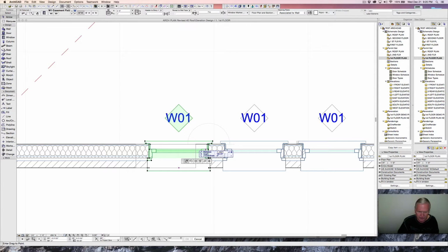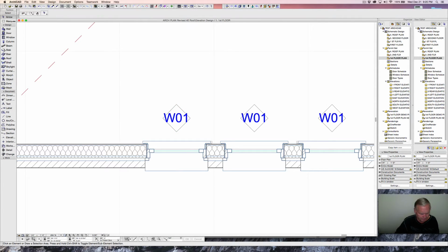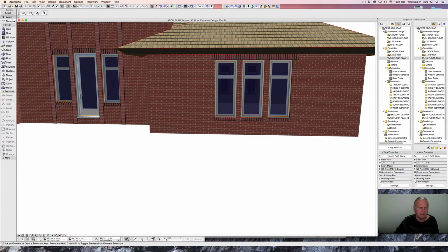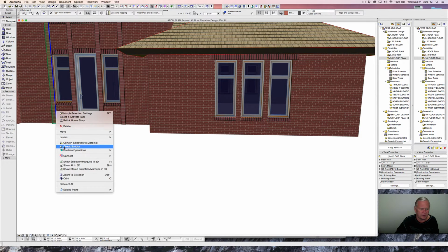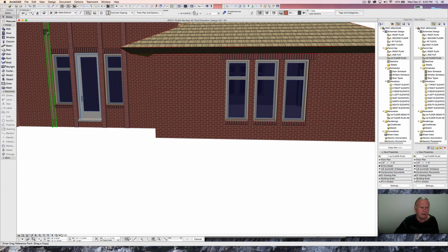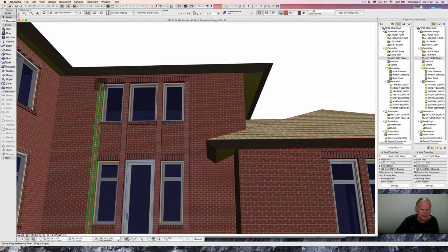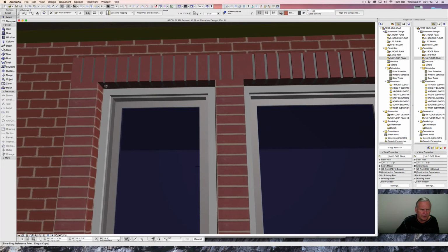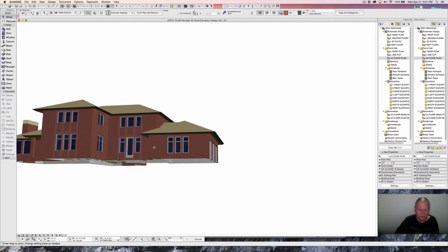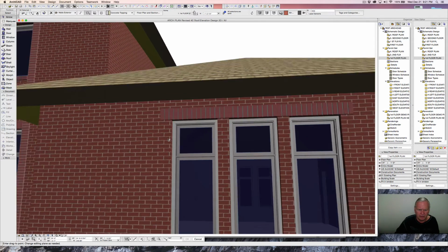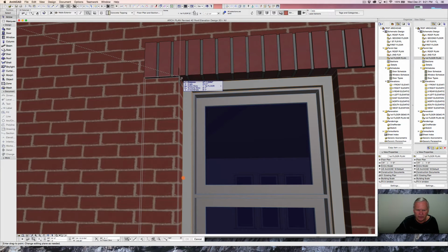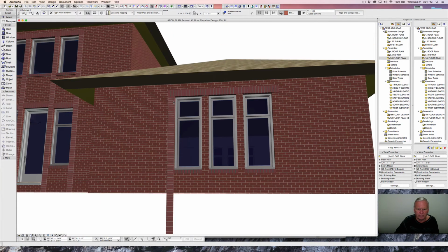1.125 inches, and we've got that moved correctly. So back to, let's go F3, and let's take one of these, move, drag a copy, and let's just go up here and find its upper corner and in the back. That one right there. Now we're in 3D, so that goes with us three-dimensionally. And I grab that because the point I was going is right there. And then that puts it in correctly.